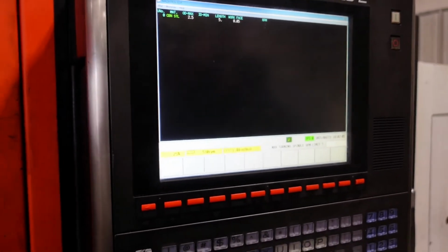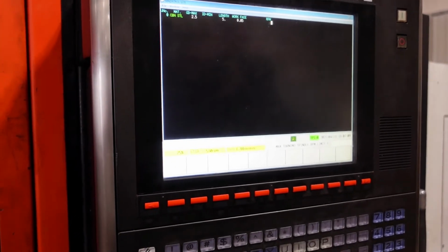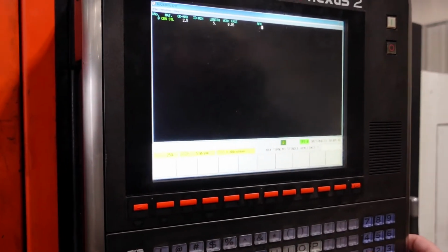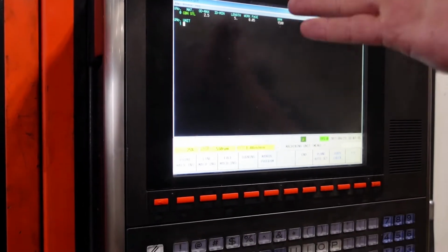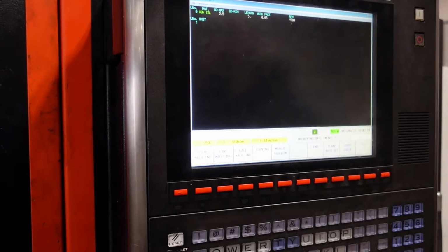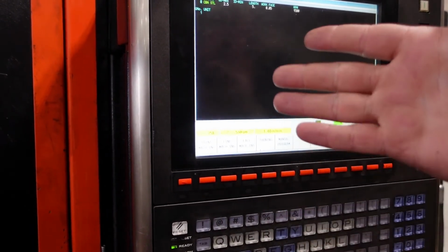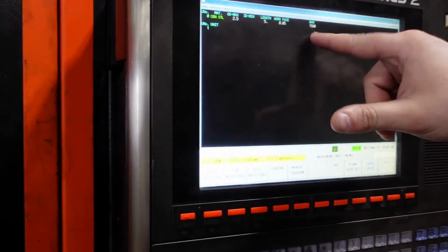Live tooling is in tool data. The live tooling, yes, exactly. The live tooling max RPM is in its tool data. This one I'll do 1500, even though it's kind of slow. So when you're facing, it will only go down to 1500. So its surface feet per minute will actually start getting smaller as it goes down, because that 1500 is going to max out.